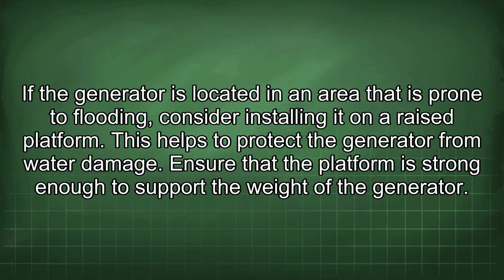If the generator is located in an area that is prone to flooding, consider installing it on a raised platform. This helps to protect the generator from water damage. Ensure that the platform is strong enough to support the weight of the generator.